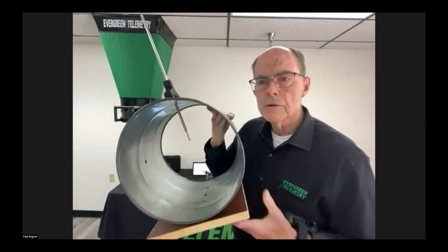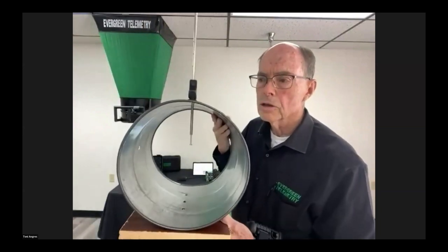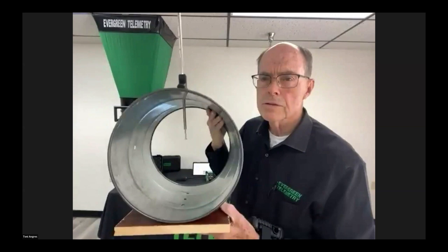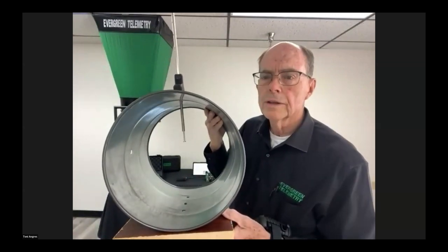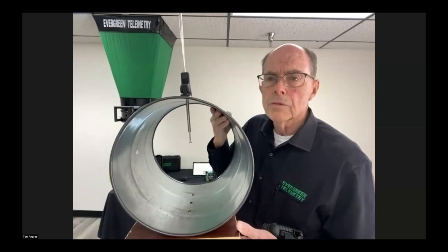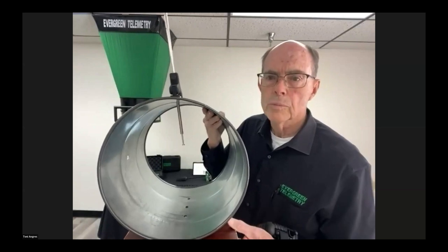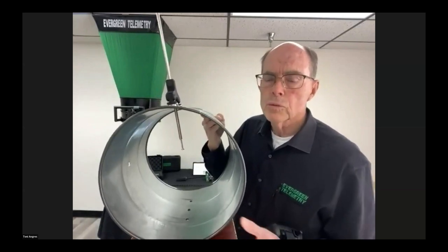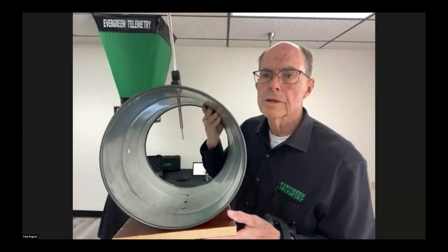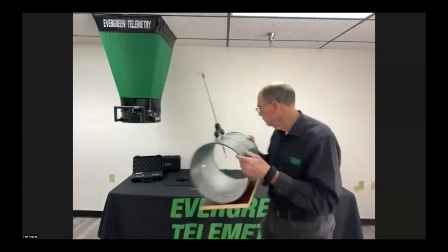Now, the result is going to come to your wrist on the wrist reporter. Now, when you go over to the damper or the fan and you're going to make a change, let's say you want to reduce the CFM by 20%. What you can do as a reference is check the velocity of the center line. And when that goes down by 20%, you're achieving roughly a 20% reduction in CFM. So you're just saving the back and forth.